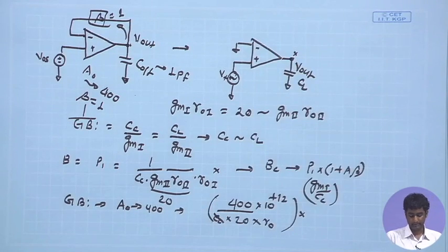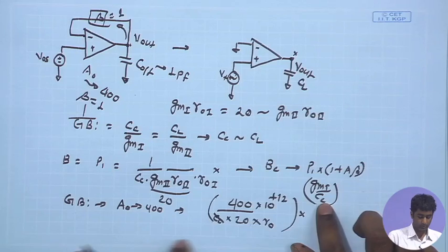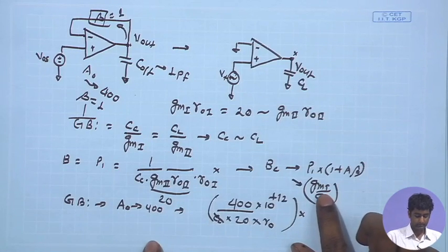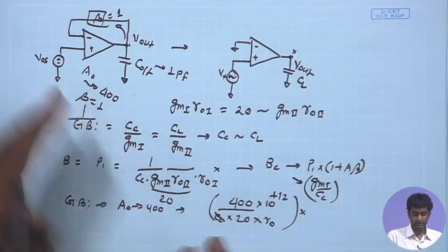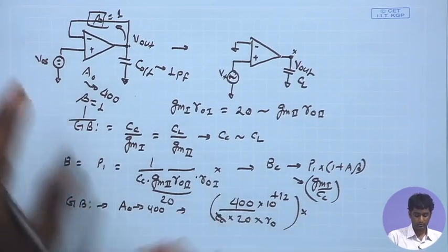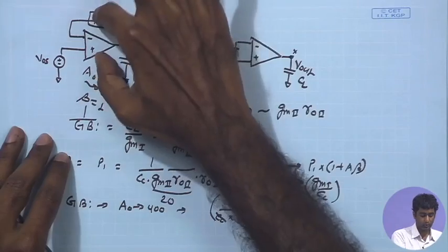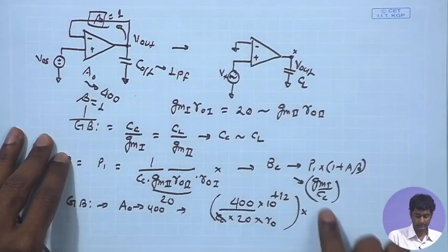So, the closed loop bandwidth, in fact, in this case is equal to the gain bandwidth product provided by the open loop amplifier, and I have to see whether this closed loop bandwidth, which is equal to the gain bandwidth product, is sufficient so that we can operate this closed loop operation fast enough with our clocking scheme.